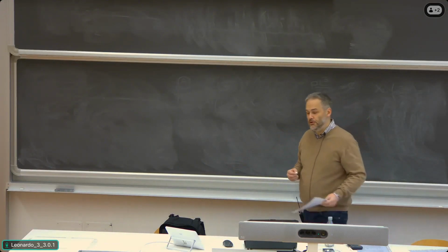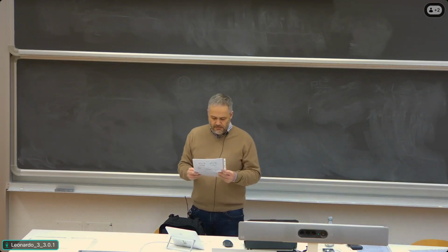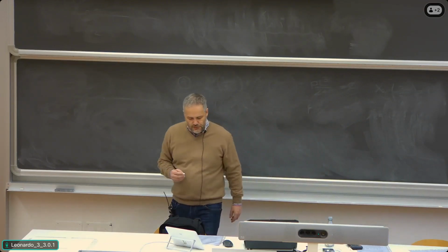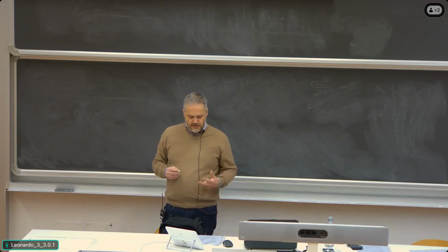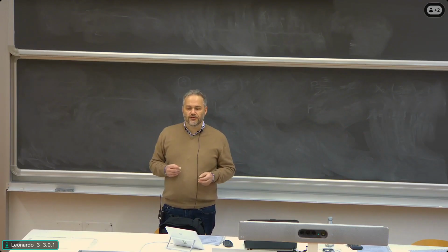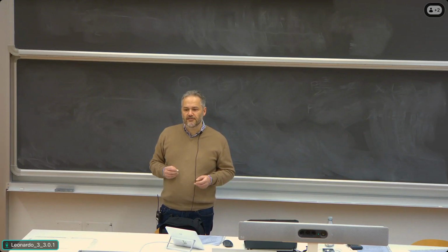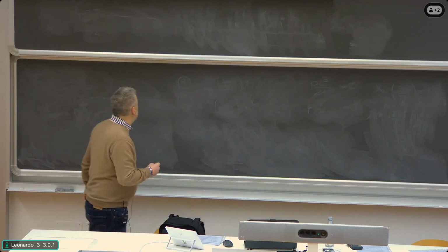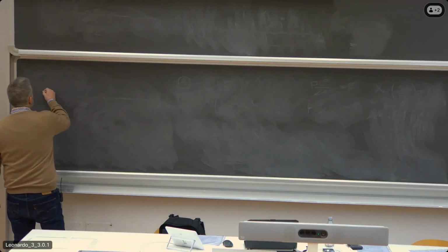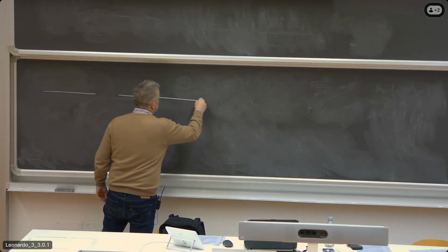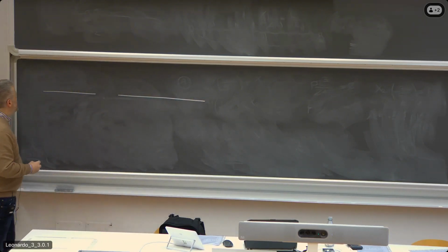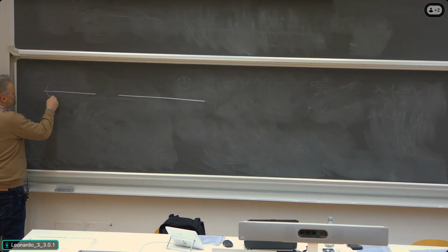Now to the second point, which read, determine the restraint forces at the four supports. A is a fixed end, so it has two reaction forces. And then we have B and C, which are rollers, so we have one reaction force each. In order to do that, it is better to break up the structure in the two spans and mark the unknowns which we just determined.